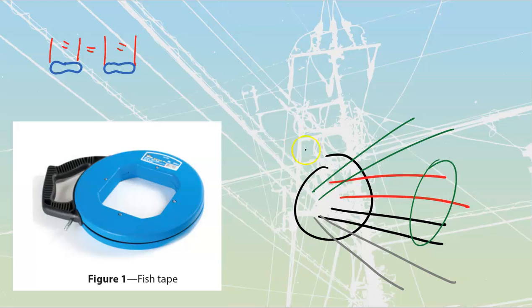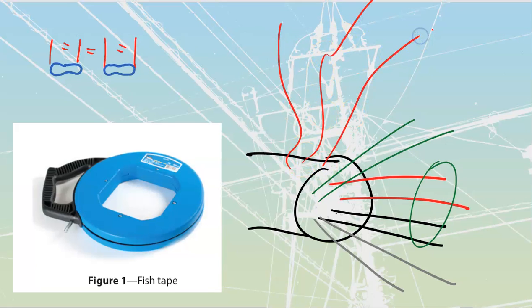Let's take a look at this conduit that we have right down here. The better this conduit is at taking heat and carrying it away, the more we can fill that conduit up, because it's going to be able to keep the conductors cool. If I replaced it with PVC, that PVC conduit would hold that heat inside and would damage my conductors.